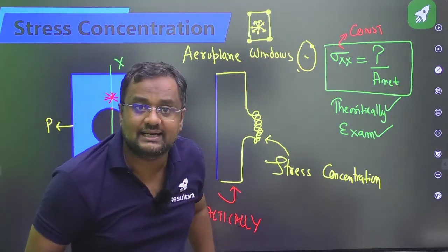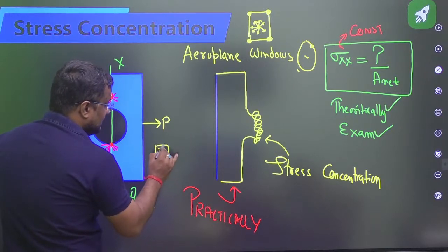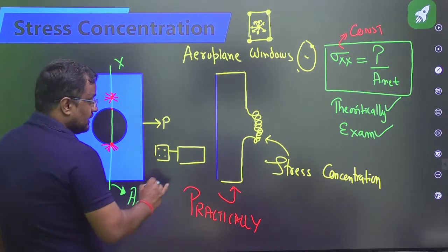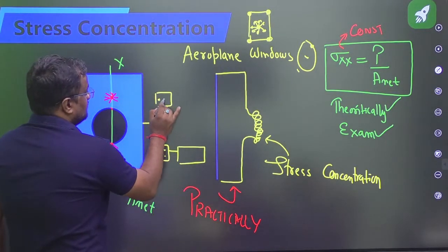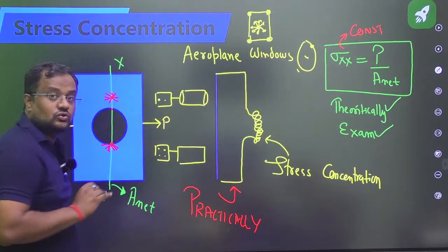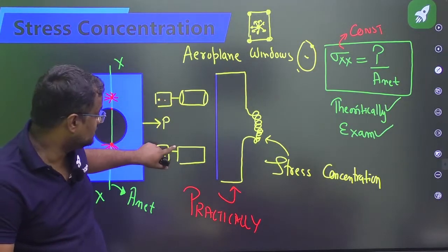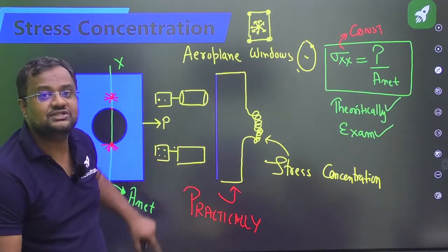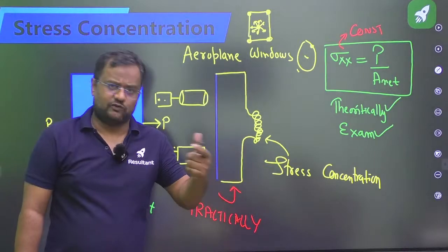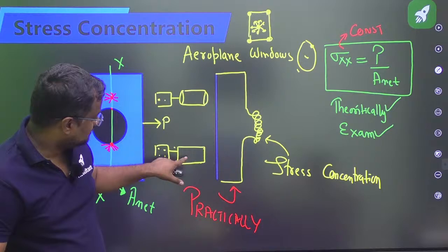Same concept, the oil tankers. Guys, you have seen the oil tankers, the oil container is not like this. The truck is like this and the oil tanker is like this, so that the curved shape helps to reduce the stress concentration. At these points, the stress concentration will be more, and leakage chances are more. In normal containers, for transporting almirahs, sofas, anything, this is fine.